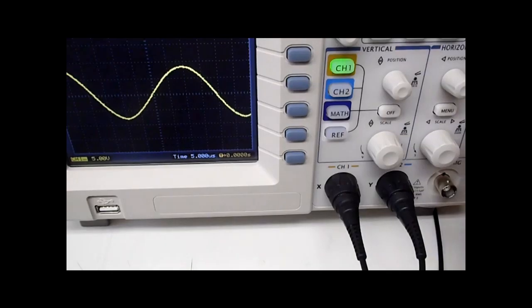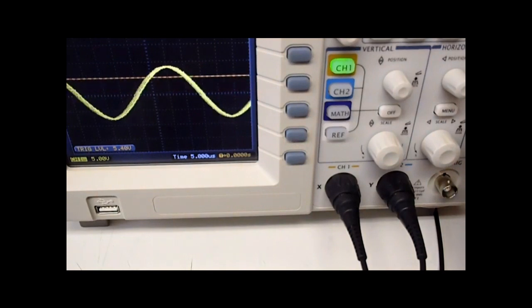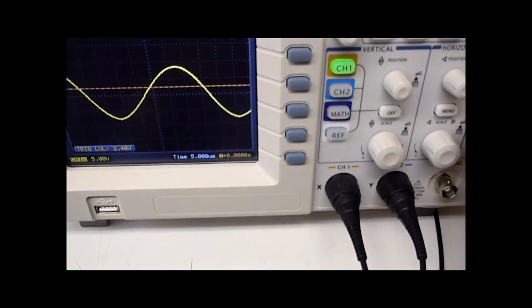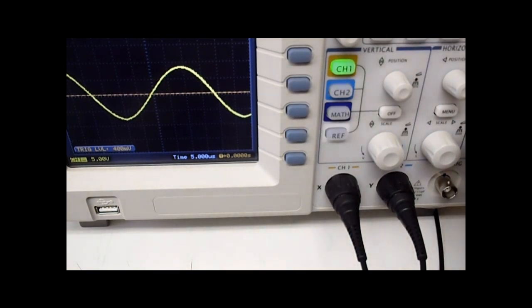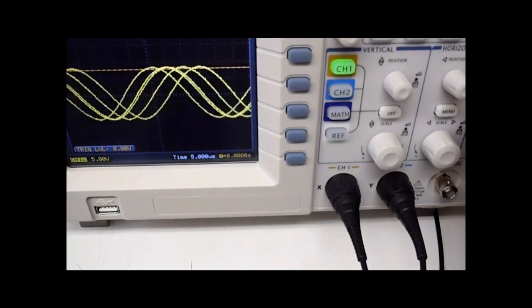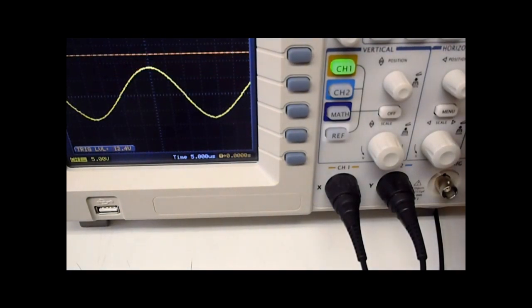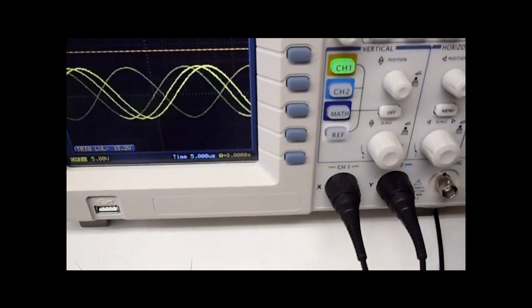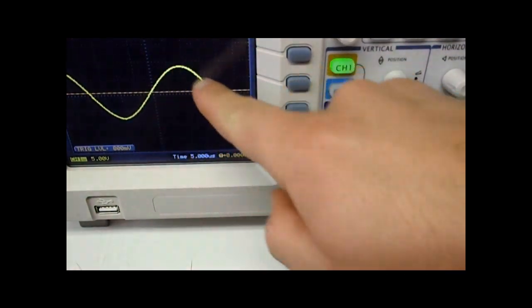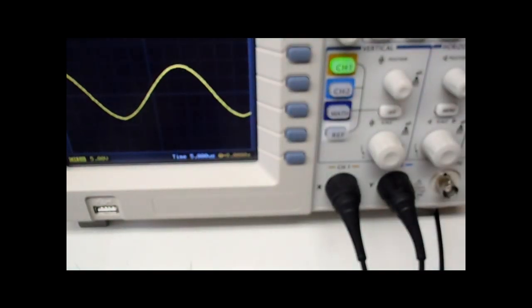Now another unique feature in an oscilloscope that's pretty well standard is the ability to use a trigger level, which starts the oscilloscope recording, or if you will, observing the waveform at a certain point. So as you can see right here, we're not really recording anything because our voltage isn't being hit, and then when we bring it down, it starts recording the waveform at that level. So it's a very cool tool for troubleshooting and doing a more in-depth analysis of what's actually occurring in your circuit.